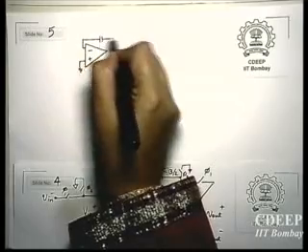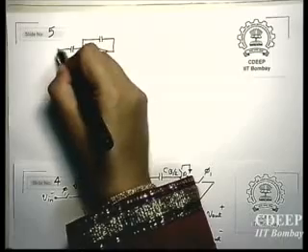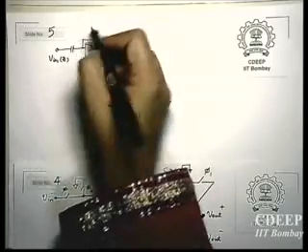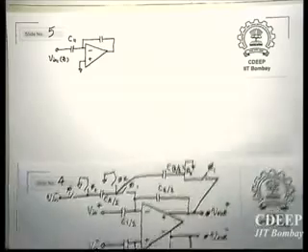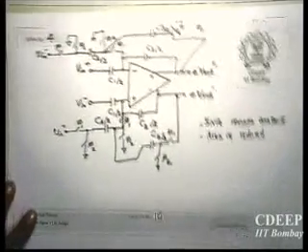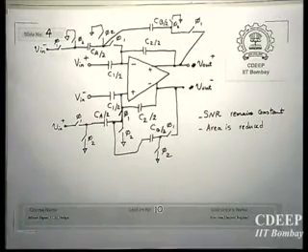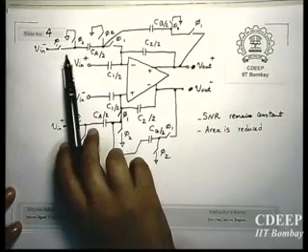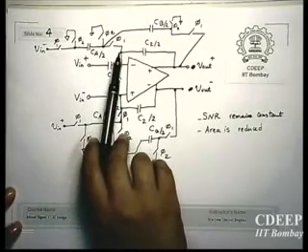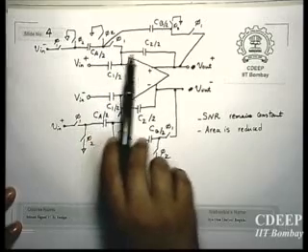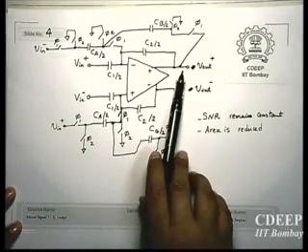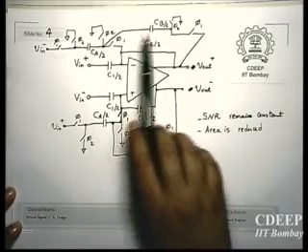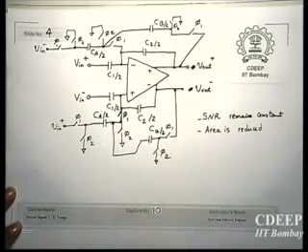This is one standard architecture in switch capacitor filters. By the way, regarding the sampling over here, at this point I need to mention, because we have used backward Euler, in phase phi 1 the entire input is transferred to output, and similarly this feedback loop will work, and in phi 2, these two capacitors CA and CB will get discharged.